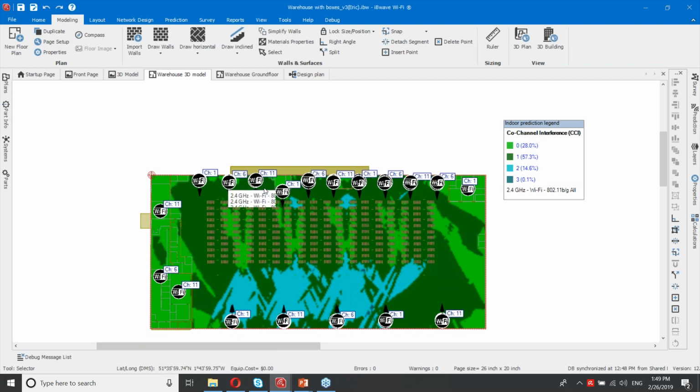I put those additional APs in the areas where I thought that the holes existed. And then in the end, if you still have some areas where your signal is a few dB lower than it should be, try lowering antennas if you mounted them high, maybe 2 or 3 meters above the ground, or experiment if you can without tilting the antennas.